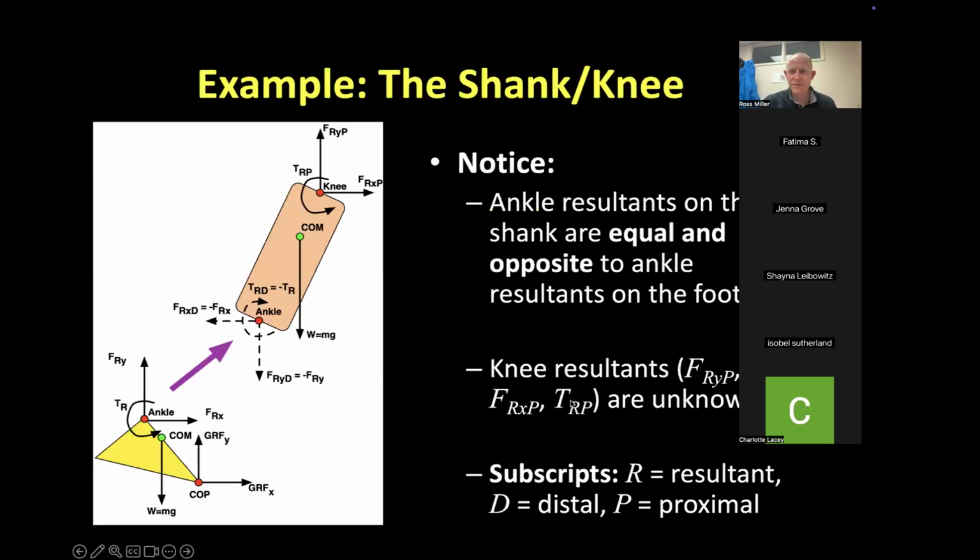Okay, so we left off here doing inverse dynamics, and this is the process by which at the joint level we relate motion to the kinetic causes of motion. Those specific causes within each joint will be two specific things: a net or resultant force at the joint and a net or resultant moment at the joint. So what specifically are we calculating with inverse dynamics? For the foot, for example, we're calculating the net resultant kinetics at the ankle. So that would be this force at the joint with both its horizontal and vertical component, and the torque at the joint with its rotational component there.